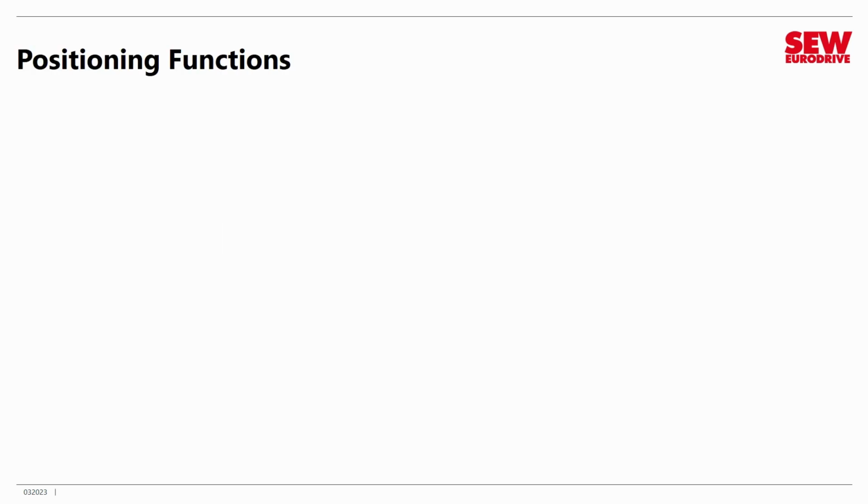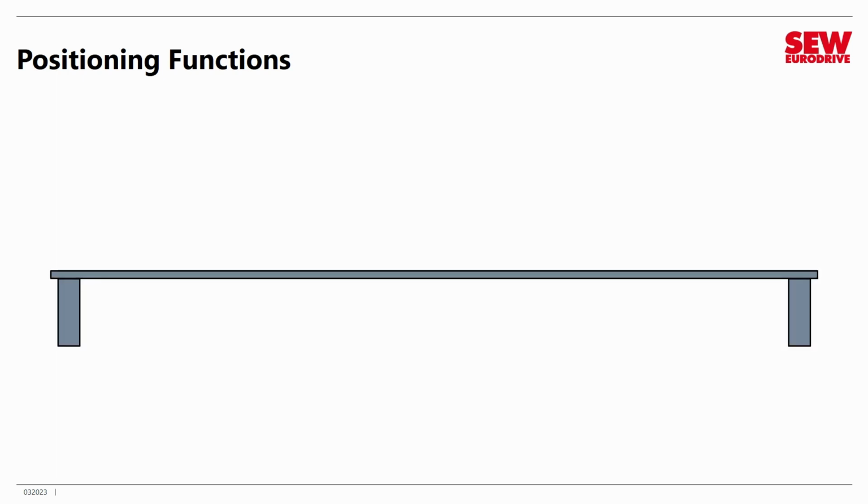We are going to do a positioning application for a canning and palletizing machine. So it's something like this. We have a long linear track. At the left end, we have our start position. You can see the little carriage that's going to move the cans, and we consider that our 0 position. So that's start. All right, next along the track, we have a can filling machine, and it's located at 30,000 increments clockwise of the start position.